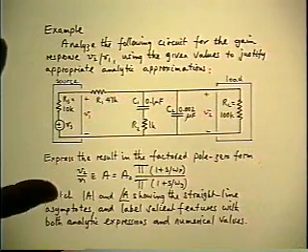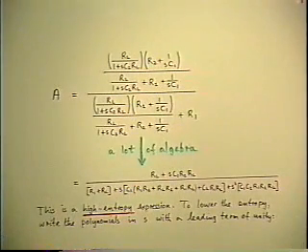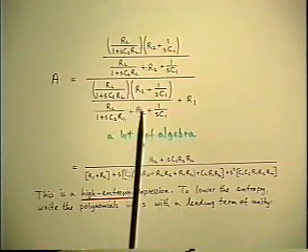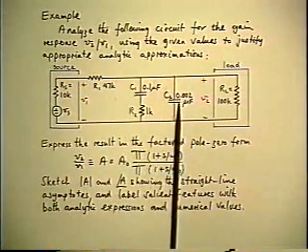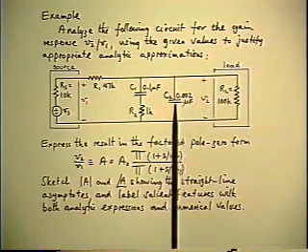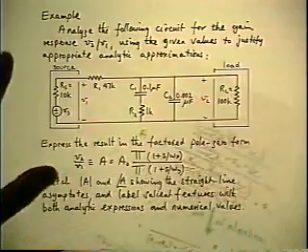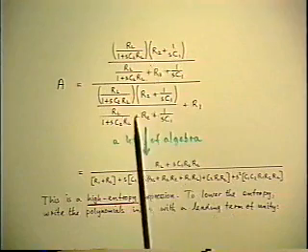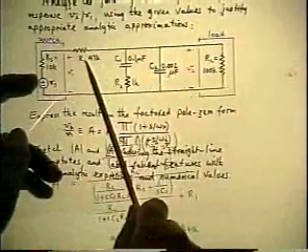Okay, so what happens is a week later they show up, turn in the problems, which are usually multiple pages, and the starting point is a huge equation which you get by treating this as a giant impedance divider, where the bottom branch is all these three branches in parallel, which is what all this mess is on the top. This is the parallel combination of those three branches, and the denominator is the same thing all over again, plus the series branch, which is R1.